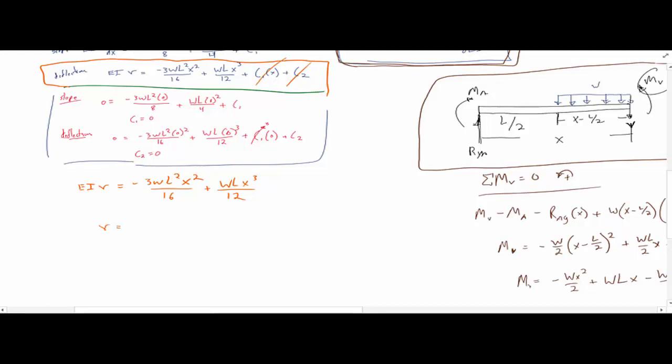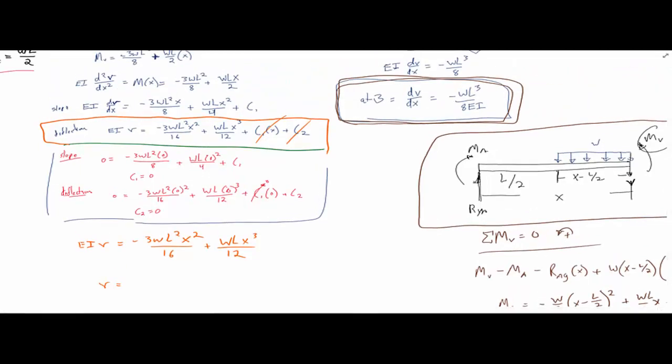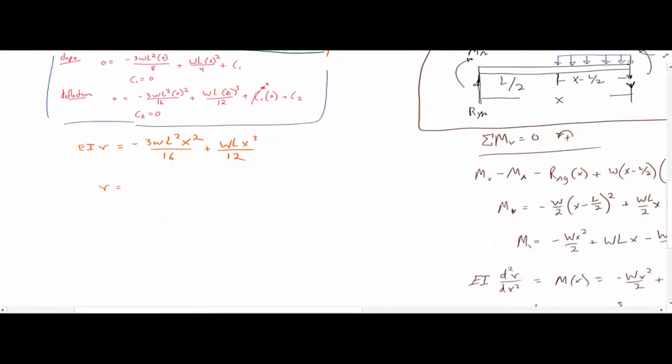And you should get deflection equals, I wrote it down, so hold on. Okay, so our deflection equals negative 7 W L to the 4th over 192 EI, okay? And that's at B, right?